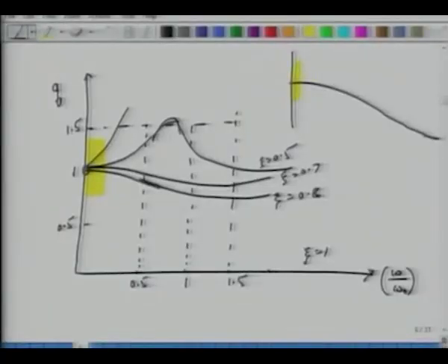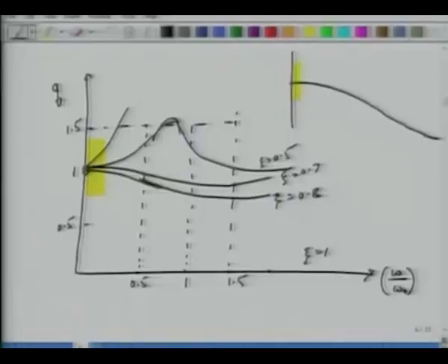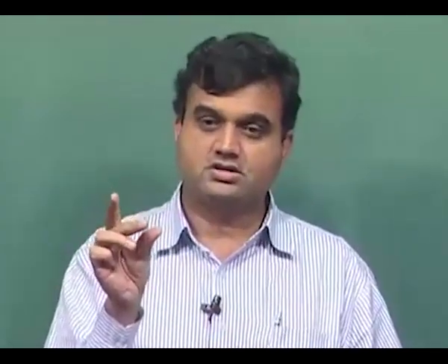Now the challenge is that if I have to measure acceleration at 100,000 hertz, then I have to maybe increase my omega naught up to maybe 10 million or a million, something like that, because it has to be very small. I can do that by reducing the size of the structure. If I reduce the size of the structure, the stiffness starts increasing significantly. So I can do that.